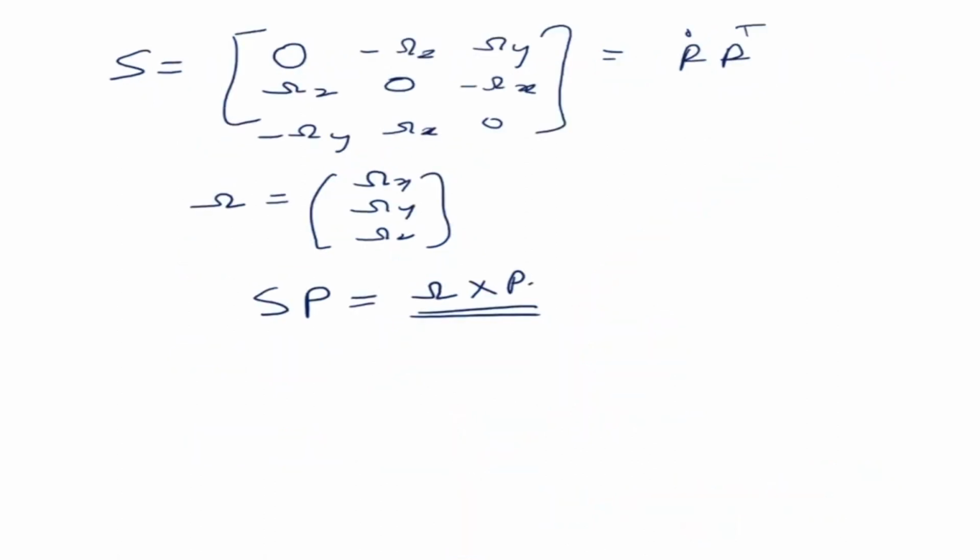Now this shows us that a body which is rotating will also have a linear velocity, and this would mean that in our manipulators, which are serial arms in which the joints are revolute joints, all the rotations there are going to cause a linear velocity in the forward joint.